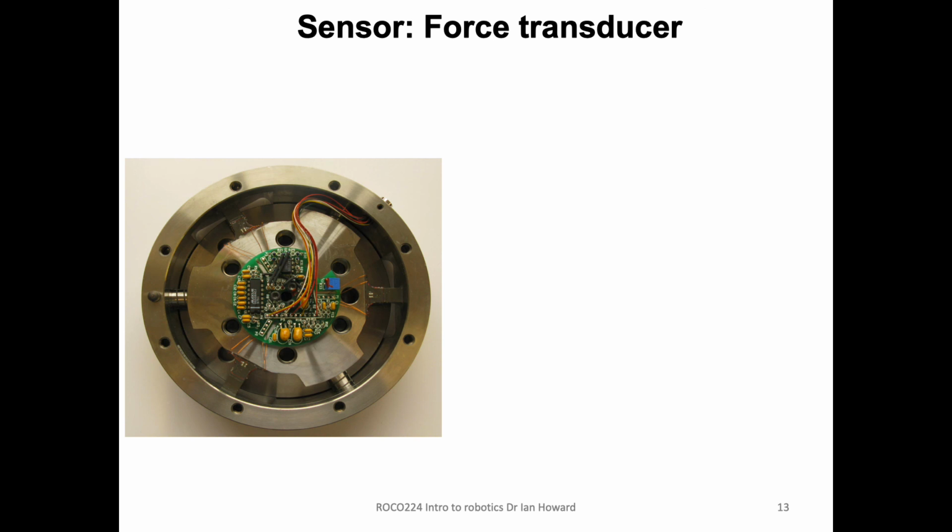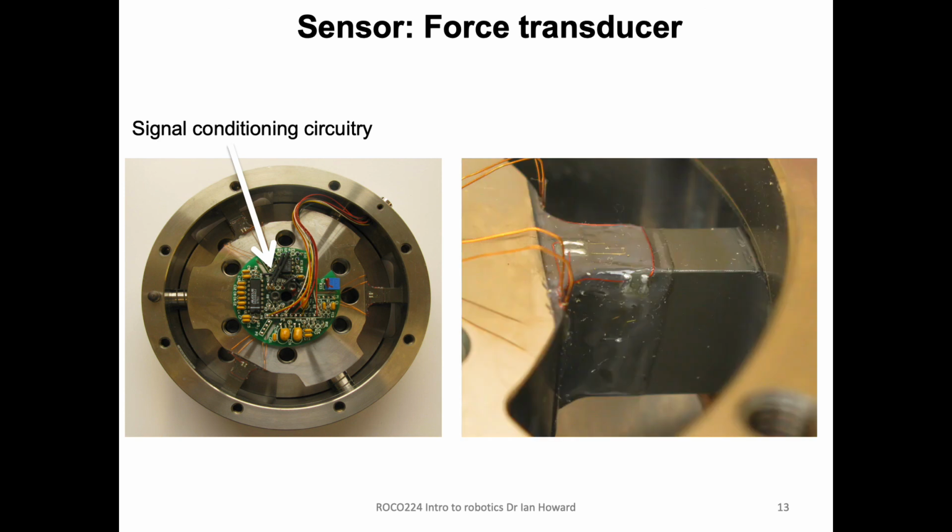Another thing we are always quite interested in in robotics is how much force you're pushing, and the way to measure this is to use something called a force transducer. Basically, it's using a sort of Wheatstone bridge arrangement, which is looking at how a resistance element changes as it gets strained. In a nutshell, if you stretch something, it gets thinner, resistance goes up, and you can have an estimate of what the force was on the structure that it was stretched by.